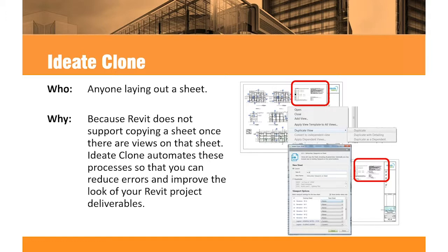That's one of the reasons why Revit doesn't have a tool to duplicate, because there's no way to really handle the viewports. We can actually duplicate the viewports, or you're going to see that I can swap relevant viewports. For instance, maybe an east dependent view with a west dependent view, or maybe a first floor architectural plan, swapping that out to a first floor HVAC plan as an example. You're going to see some examples I have of being able to duplicate and still control those viewports.